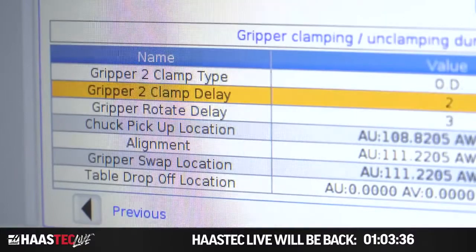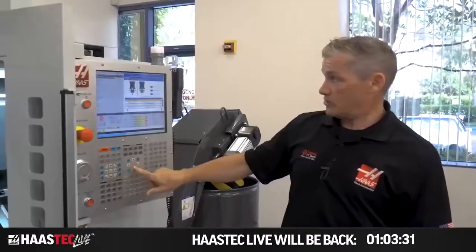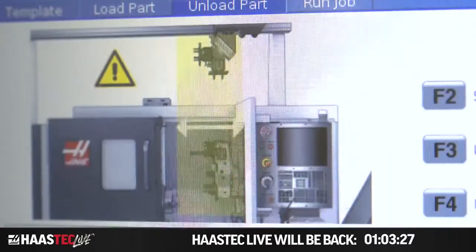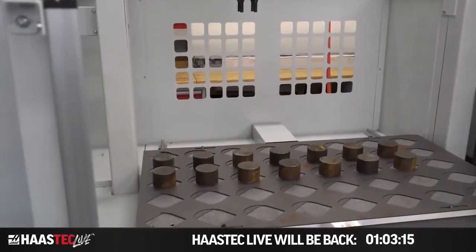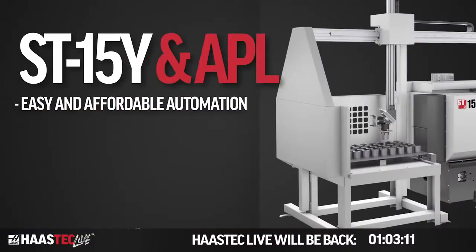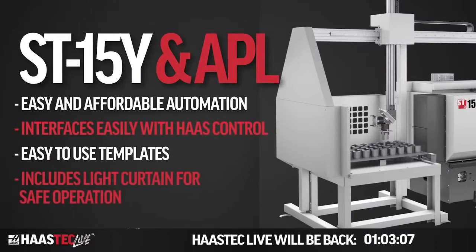All of that is controlled from within the HaasTech control here. So you use a series of VPS templates. It just walks you through. I've got these GIFs on screen here to show you what you need to do. And then to jog the machine, you're going to use the remote jog handle, in this case, our new touchscreen one. So it's very easy to move the APL arm into the position that you want to program, turn on APL mode, and the thing works automatically. If you don't need it to work in that mode, you just turn that off and use it like a regular lathe. Pretty straightforward. Let's throw it back to Brian.